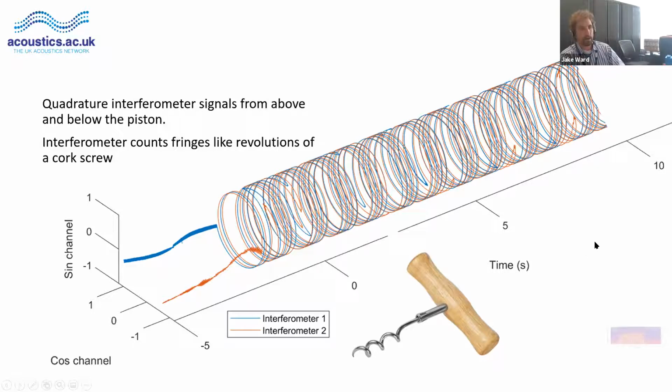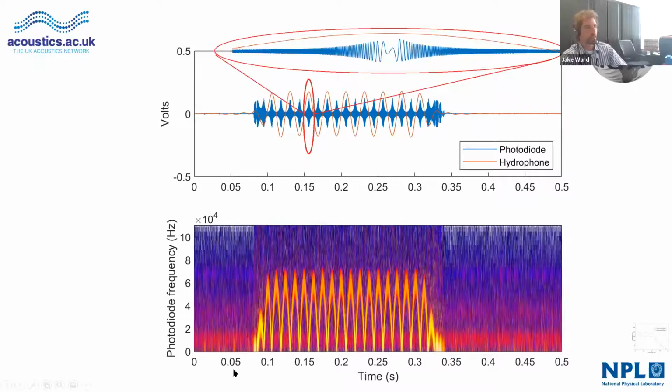so from the phase of the interferometer we can infer the displacement to sub-wavelength. The wavelength of light we're using is red, 630 nanometers, and so each fringe is half that, 300 nanometers ish, and we can get down to about 30 nanometers accuracy with the noise on the electronics. And like I said, for a sinusoidal drive of the displacement, that's actually a chirp in the frequency domain of the photodiodes in the system. So as the velocity of the piston increases, we get more fringes per second.